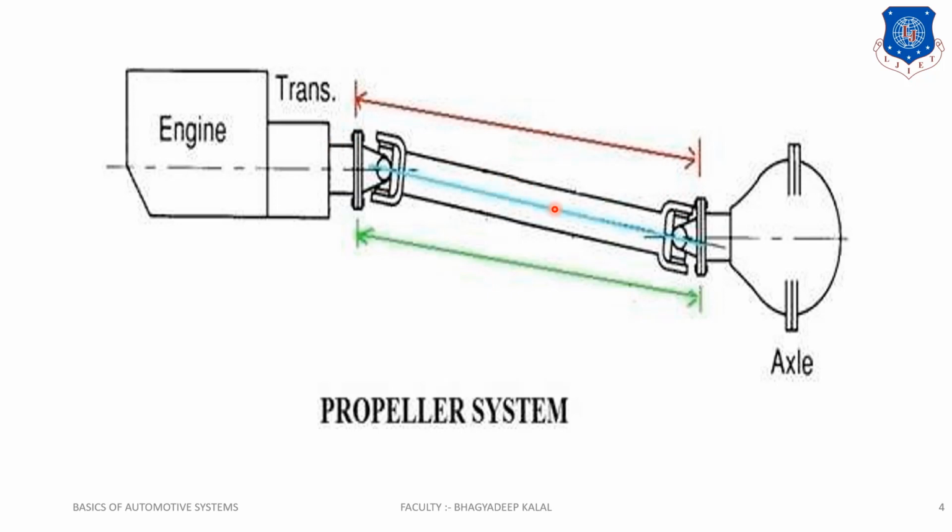Why is a universal joint connected? Because it can transmit power at an angle. An angle is made here, and similarly an angle is also made here. So by using this universal joint, power can be transmitted at an angle, and the angle is permitted up to 18 degrees. This is our differential mechanism, and these are the rear axles.